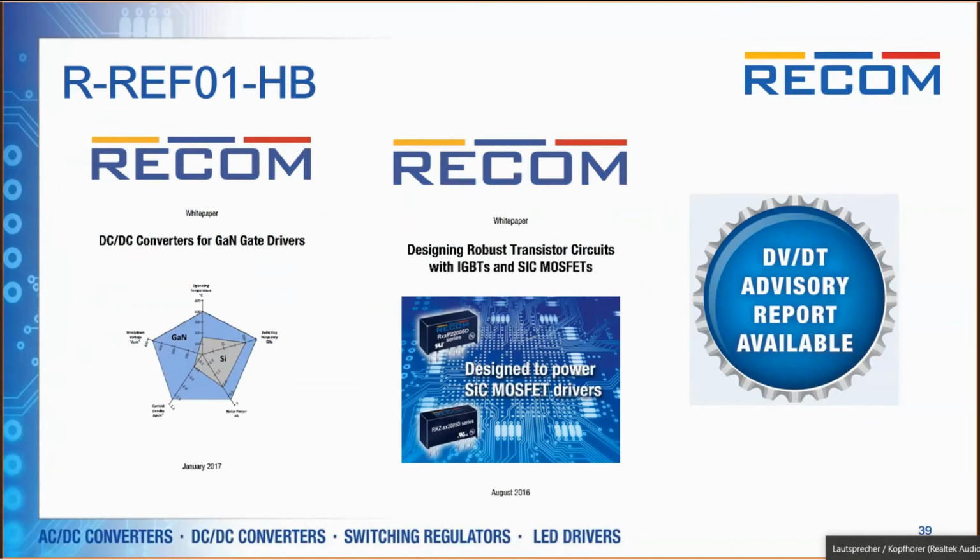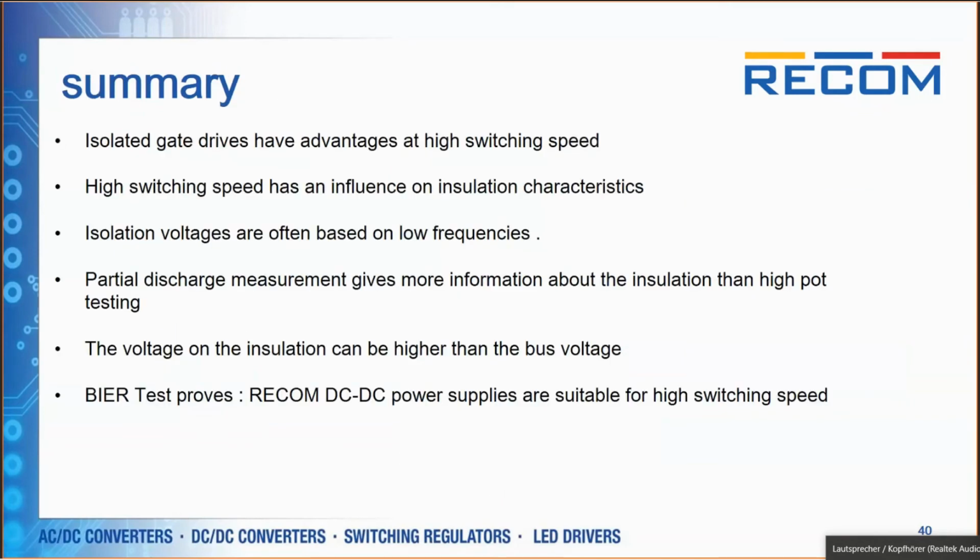So we have a little bit more information about this topic. The complete dV/dt advisory report, which was written by Dr. Sommereder, you can download. And also we have some white papers for gate drivers for IGBTs, SiC MOSFETs, and GaN. So let me summarize. The isolated gate drivers have advantages at high switching speed.